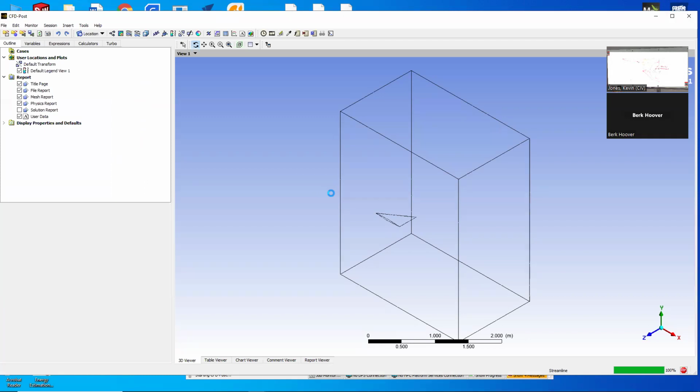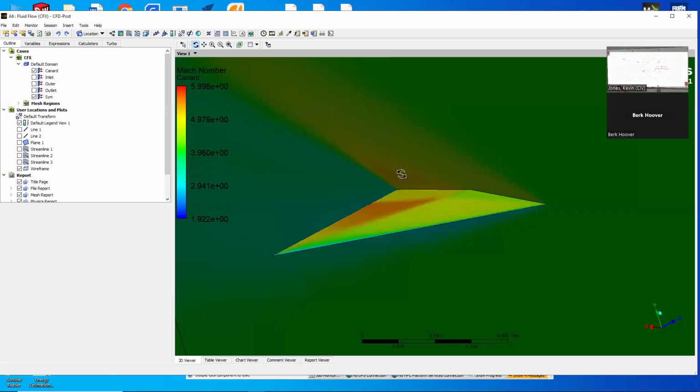So the domain's big for Mach 4, but it's about right for subsonic. I didn't want to make two domains and mesh twice, so I just left it. The stuff out here doesn't cost you anything in supersonic because nothing's happening. It costs you a little bit, not that punchy. But in the subsonic, it needs to be big enough.